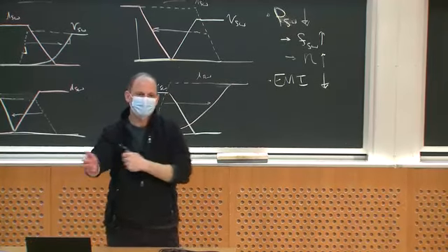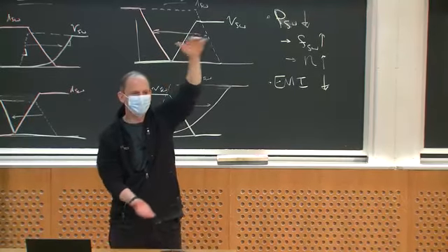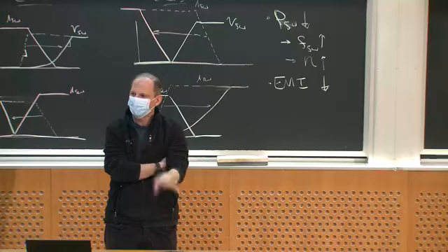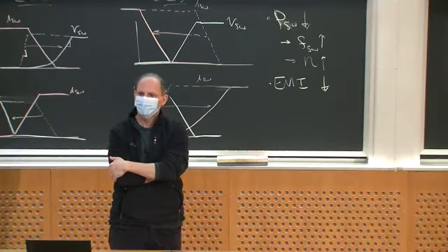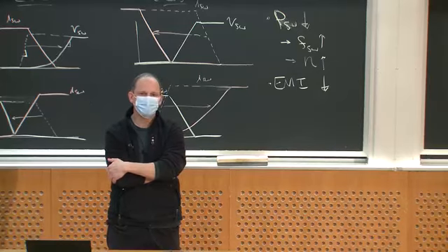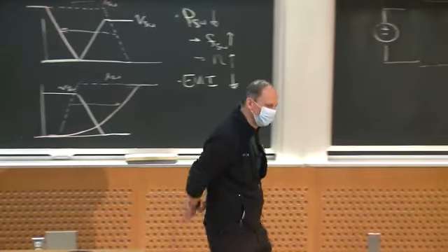So I can work out the math that says how negative the negative current has to be, how positive the positive current has to be, to create a current-based switching cycle that will always give me soft switching and will let me deliver either positive or negative average current into the capacitor independent of the capacitor voltage. Okay? And hence, I can deliver a low-frequency AC output component by modulating the positive and negative peak current over a cycle. The exact values that you need to do that make for wonderful homework problems, not that hard to work out.